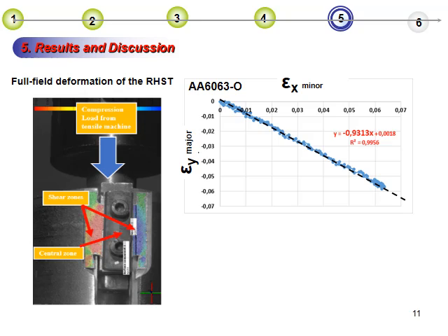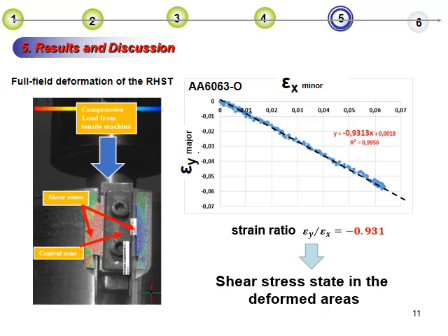This figure shows the shear strain contours in the shear areas measured using DIC. One can see the quasi-homogeneous strain field in the vicinity of the shear areas, with expected local edge effects. From the acquired strain field, the representation of the major strain versus the minor strain shows that the proposed shear specimen undergoes a shear stress state with a strain ratio close to -1.